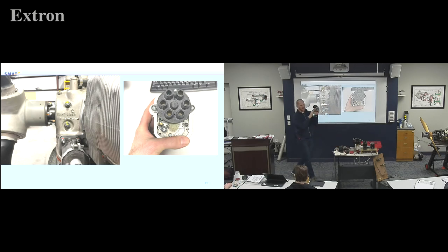So, if I've got a left hand magneto, when I spin it around and look at the wires that are going to connect to the back of my magneto, it's still going to be left. So even though I spun my magneto and you'd think it'd reverse, it doesn't reverse because the gear did it for you. So, just so you don't all confuse yourself on right or left, I can't remember, does it reverse or not? The gear reverses it from the shaft to the output. So you're using the same thing. If I look at it, if it's a left, this is turning left, but also the spark is going to travel in that left direction, which I'll show you on the board in a second.